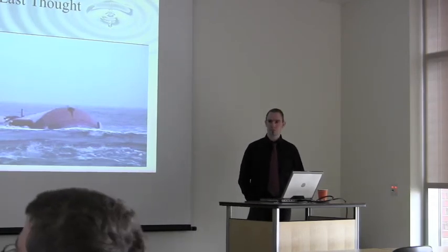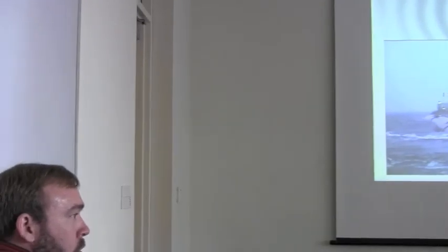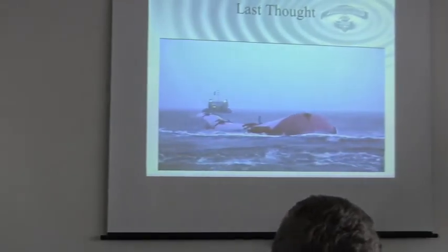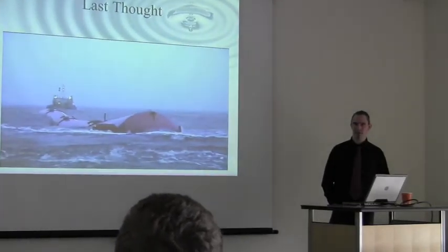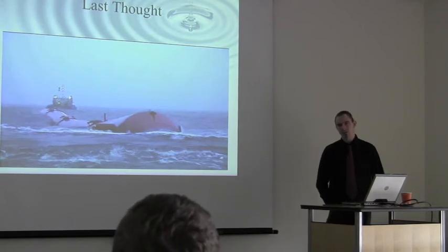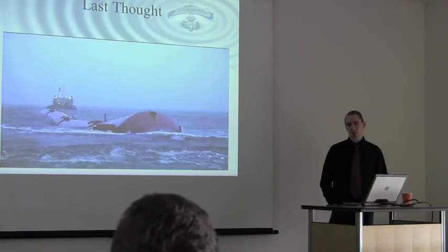I think the other thing there too is that typically when you have a heaving cylindrical wave energy converter, it's the relative motion between a spar and a buoy. The float is driven by the surface displacement of the wave, and the spar, since it's a long skinny cylinder, stays relatively still. And it's also a tension mode or spread mode or something. There are other reasons why it stays still and the float moves. So it's not a definitive answer.